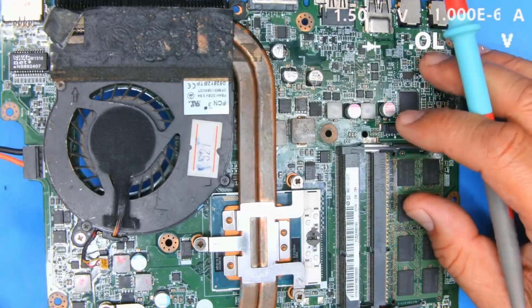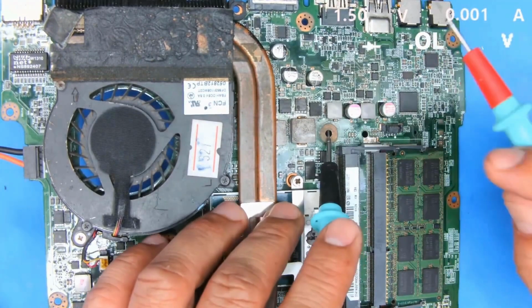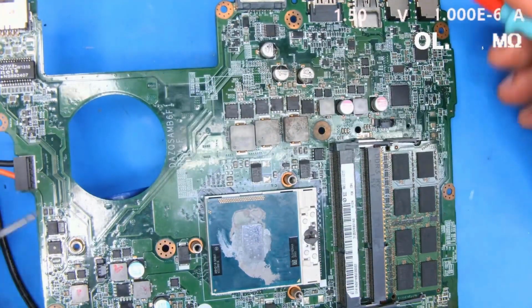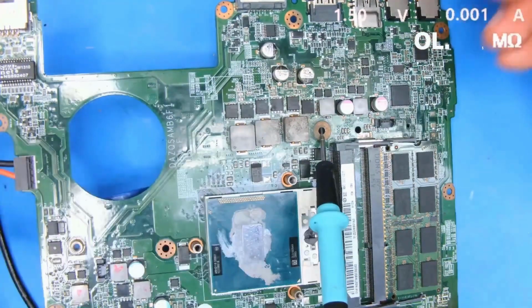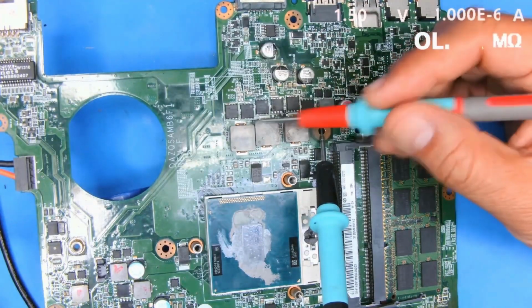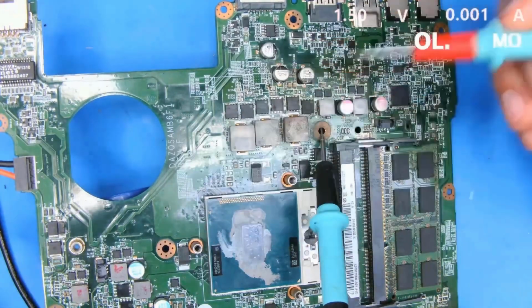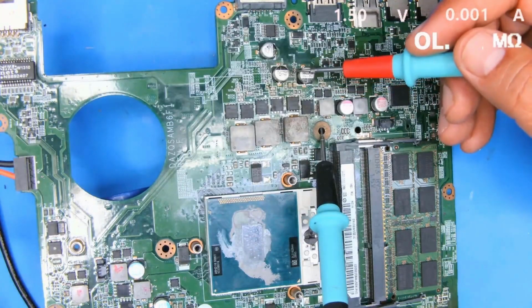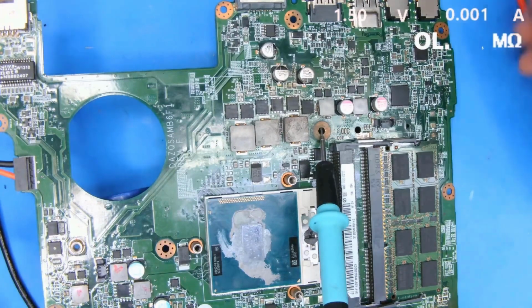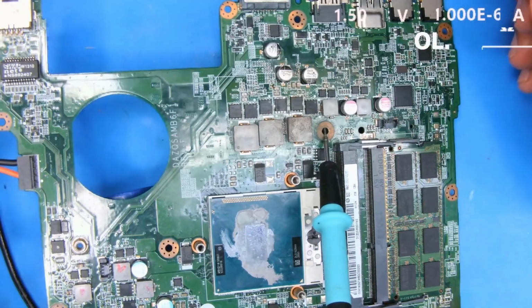Next, we'll talk about checking for a high-side MOSFET short. In cases where the short is at a shared coil position, this clip will teach you how to measure the high drive FET when there's a short involving multiple connected coils. For example, in CPU or graphics card positions, there are often several coils linked together. Especially in gaming laptops, there can be even more. So how do we know if it's a high-side MOSFET short and how do we measure it? Let's continue in this section.